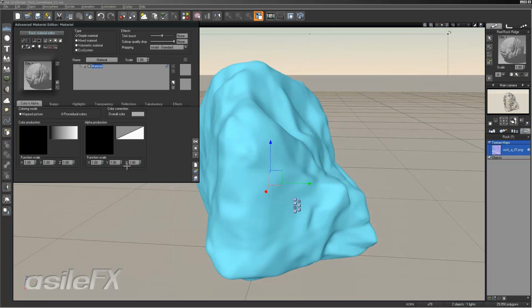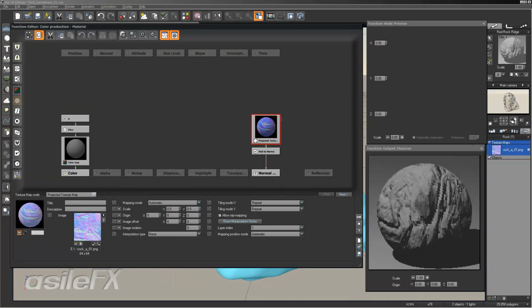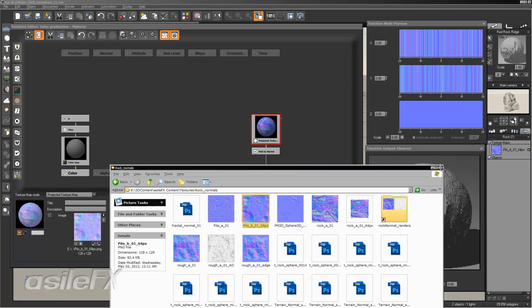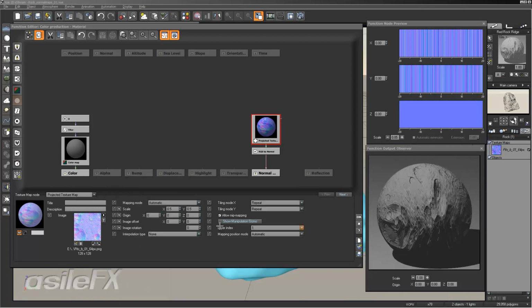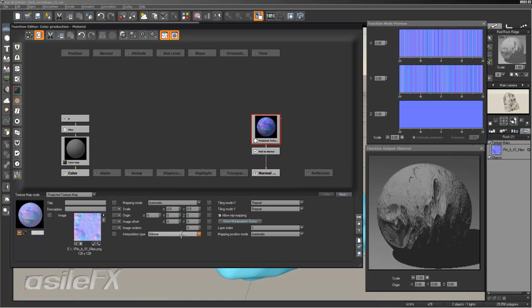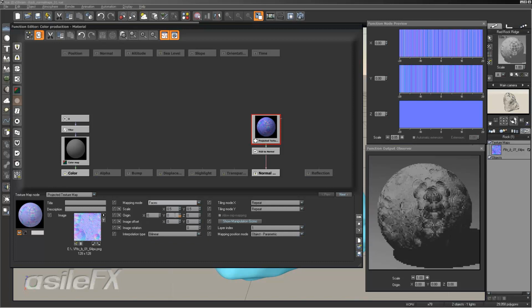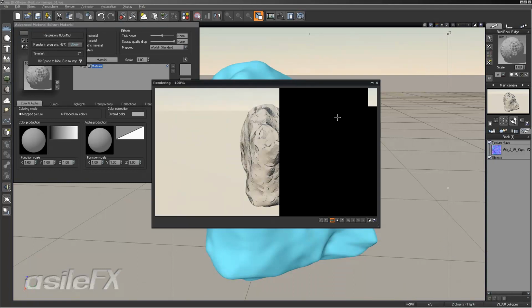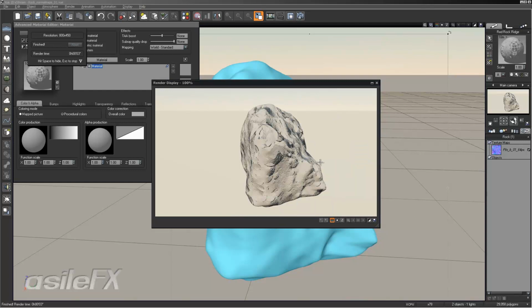I am going to go ahead and replace that texture map with a lower res one. I've got one here that I rendered, created in Vue. That's 128 by 128 pixels, so quite a bit smaller. Change the interpolation mode from bilinear, set it to parametric, and I'm going to go ahead and set this to faces. So we still get a lot of definition on it.